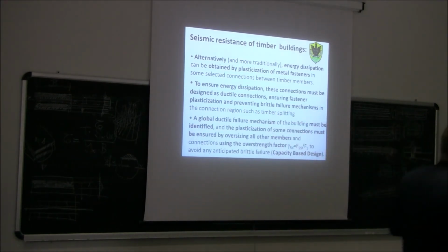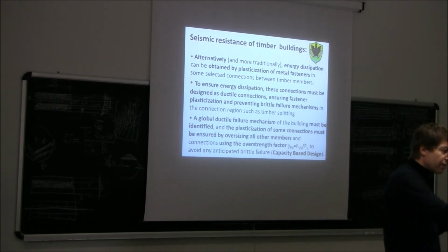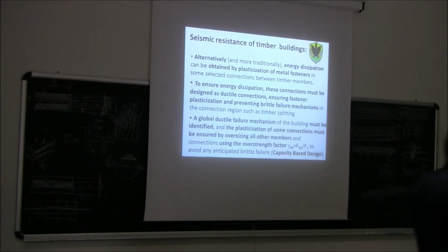So in other words, once you did the analysis of your frame under your reduced seismic forces, you calculated the envelope of the shear, the envelope of the bending moment, and then you did the design, for example, of the beam.